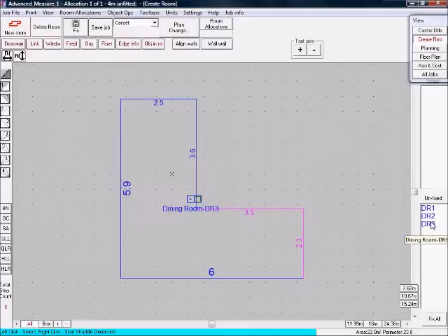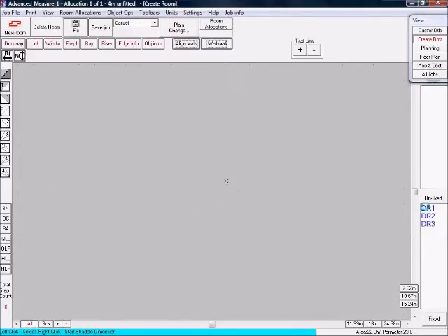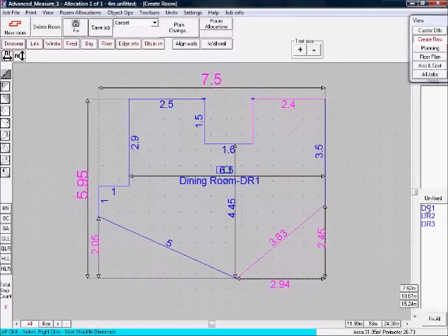In this video, we will look at how to draw and dimension rooms which are more complex. If you know the tools at your disposal, you will also find these rooms straightforward. We will look at the following tools: dimensioning from one wall to another, aligning two walls, for example, where a fireplace separates what is actually one common wall, dimensioning where there are diagonal walls, making dimensions variable which have already been given a dimension, and zooming in on a complex part of a room to see the wood from the trees.